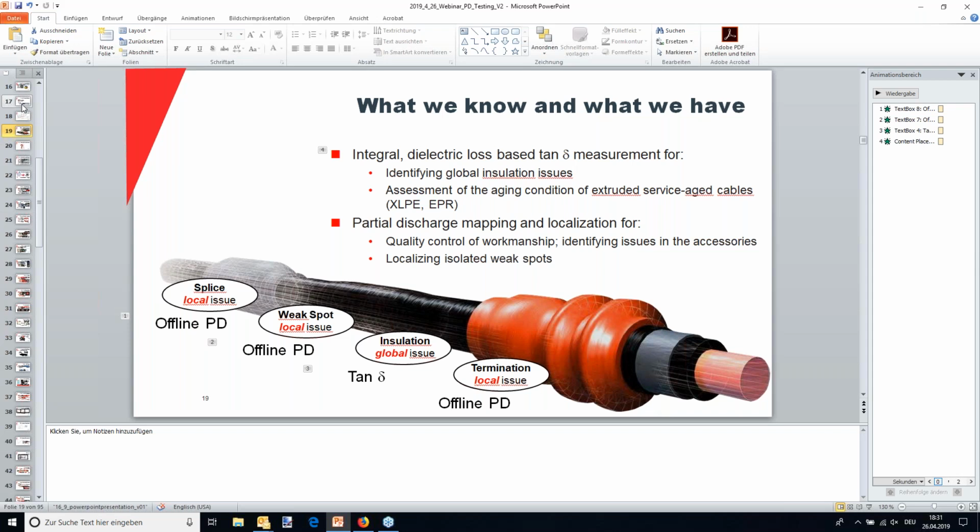And then the type testing procedure is typically going up to 4 times U0, 4 times operating voltage, and any batch that comes out of the extruder that is more than 5 picocoulomb or approaching 5 picocoulomb gets disqualified. And then they will look at the process. Hey, what's going on? We have contamination, we have problems. So yes, the PD occur mainly in the accessories if they are there, because that's also what humans touch, right? That's the workmanship related thing.